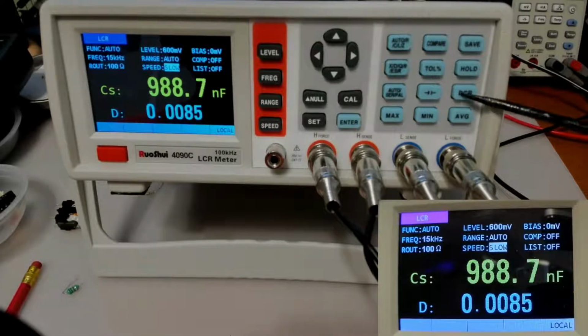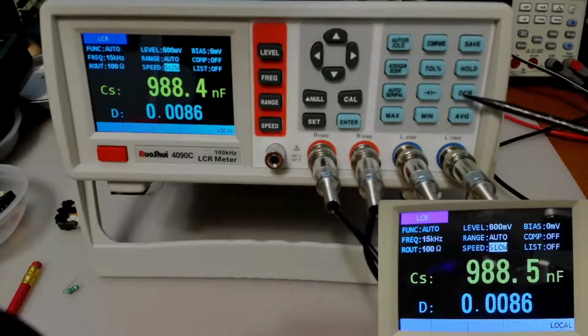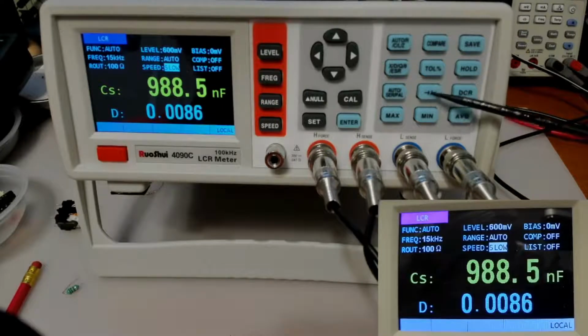This will also discuss DCR, DC resistance. For instance, if you want to know what the resistance of an inductor is without the AC component, in other words, it will just measure the resistance like a multimeter does with DC. You can push that button. If you are measuring a capacitor, this is specifically for electrolytic capacitors, or in fact other components that need a bias.